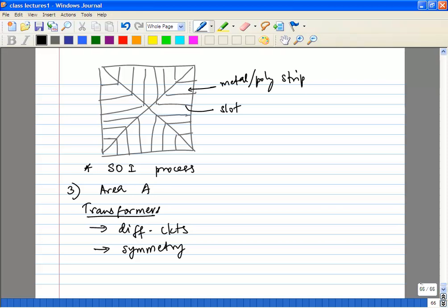So let's say you are going to design a transformer. What else do you need? You want your mutual inductance to be as high as possible. In other words, your coupling factor, which is usually K. You want to increase it as much as possible. And there may be certain cases where you are interested in a specific K, where for proper operation of a circuit you want, let's say, K equals 0.8, a coupling factor of 0.8.